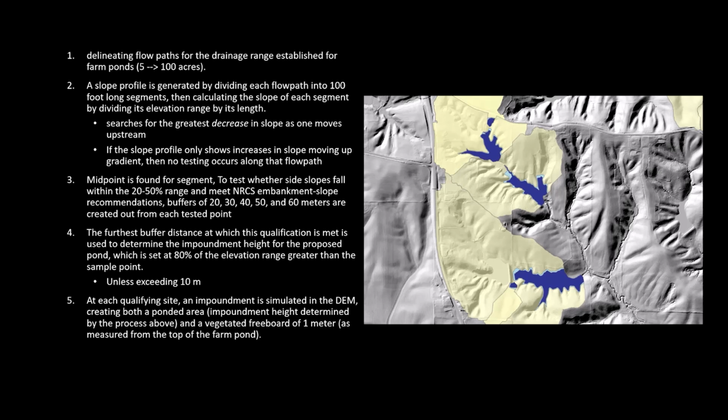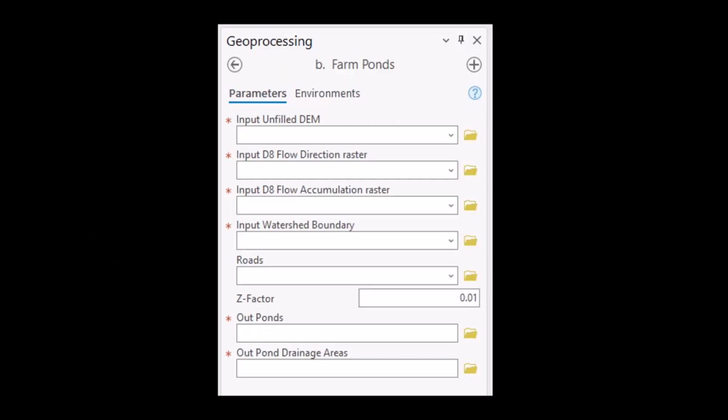If a site is found to meet this suitability criteria, the site is then kept and used as an output feature class. You'll probably notice that the user cannot change or adjust any of the criteria within this tool. Construction for farm ponds involves significant excavation and earth moving, which changes local site topography drastically. This tool aims to identify locations most conducive to pond construction, where earth moving costs may be reduced, but it does not provide any inventory of all locations where pond construction may be feasible.